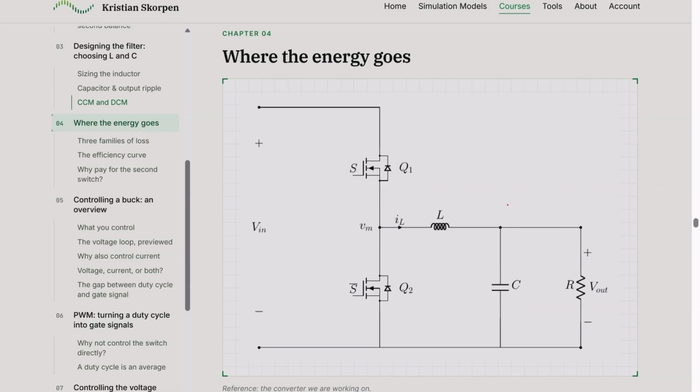And the second type of losses is associated with the switches. So it is losses that come when you're switching. One loss is, for example, driving the MOSFET itself. That takes some power. And the other loss is when you're switching itself. So for example, if you have a voltage at this level, and then you have a current at this level. So let's say that this is current.